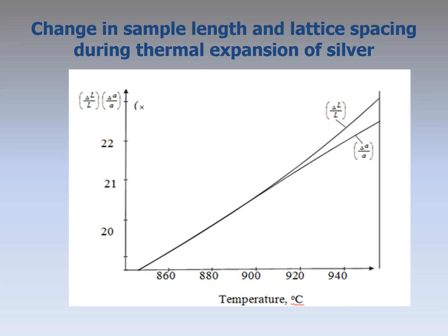In another group of methods, experiments using quenching are used. Excess concentration of vacancies obtained during quenching from high temperatures gives an increase in the specific electrical resistance ρ.